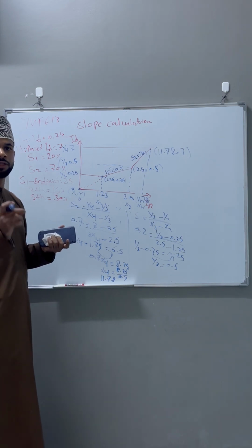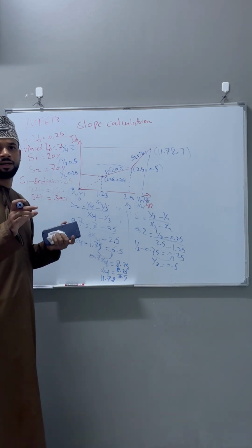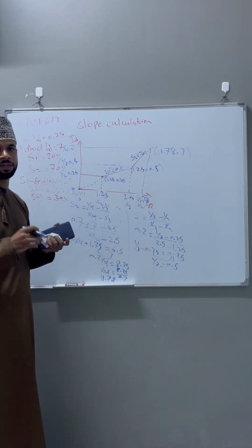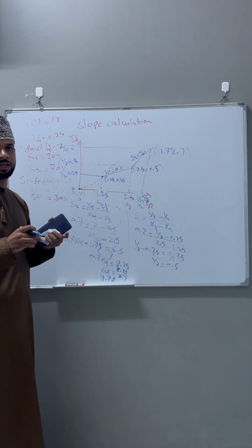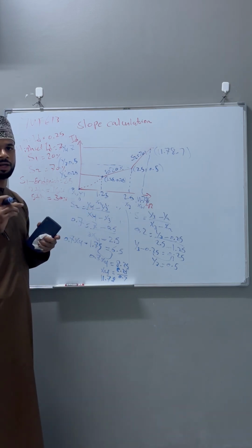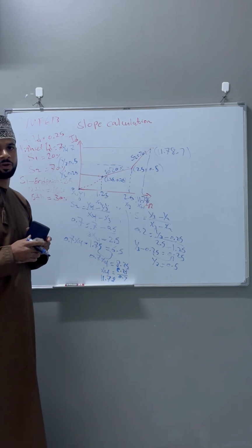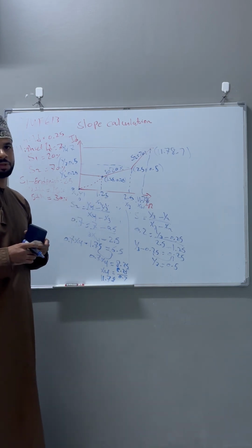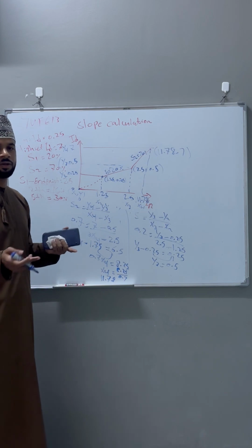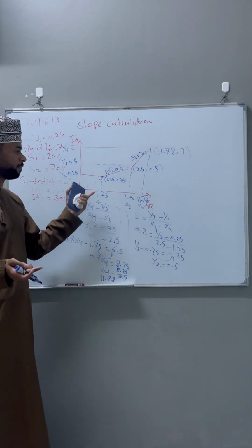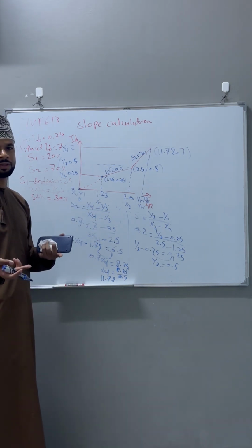So if you enter the wrong restraint formula, the transformer differential relay will not give an accurate result, or the test will not pass.